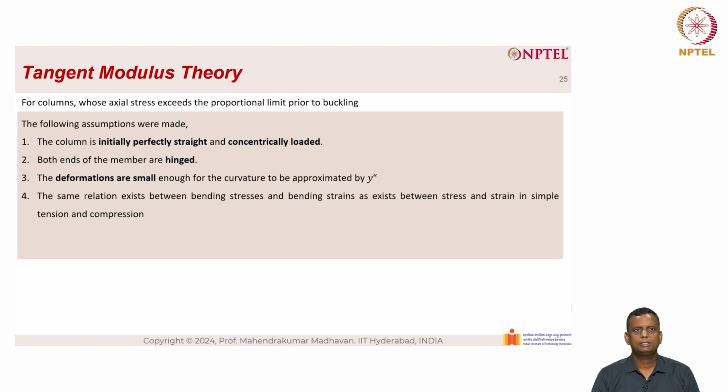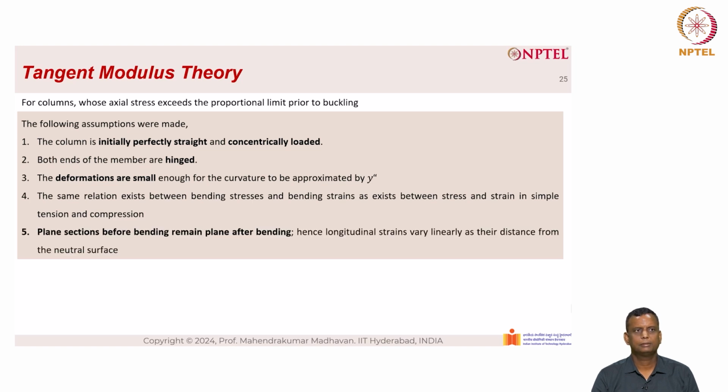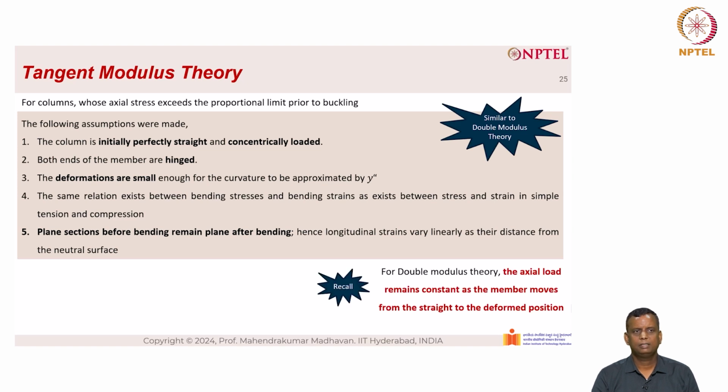The same relation exists between bending stresses and bending strains as exists between stress and strain in a simple tension and compression. Plane sections before bending remain plane after bending, hence longitudinal strains vary linearly as the distance from the neutral axis. So this is very similar to the double modulus theory.